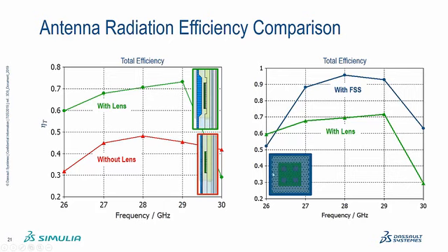If we then take it further, not only thickening the cover locally, but actually specifically engineering a window, so this frequency selective surface window for the back of our phone, we can improve the efficiency by another 20%, so almost doubling the efficiency. This has an enormous impact because it means that you're requiring much less power to sustain a good communication link. That means that you have a much larger battery life for your device. So even from a systems engineering point of view, it's very important that the antenna engineer has an input or has an influence on the overall phone cover design for millimeter wave applications.